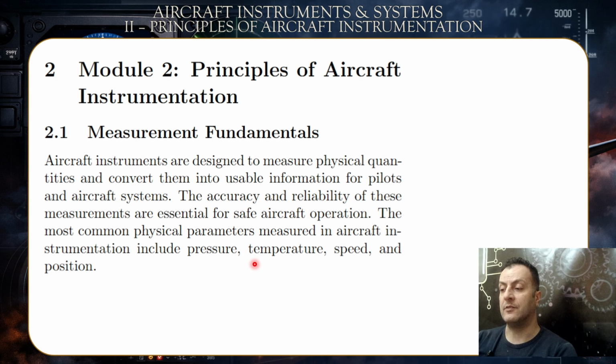The instruments do that, by changing the needle based on that pressure differential, I can actually read on the display the value of the actual altitude, the airspeed, the speed of the air moving through and around the aircraft, which is actually the speed of the aircraft within the air. And also the VSI or vertical speed indicator.